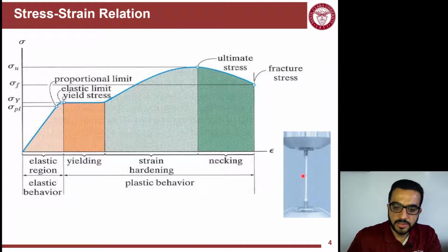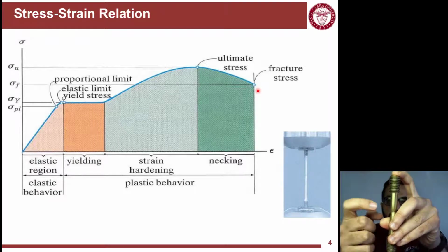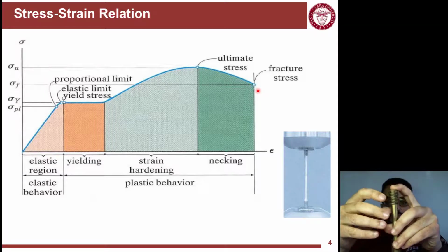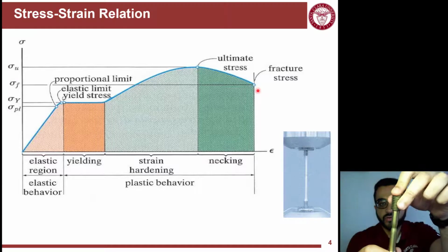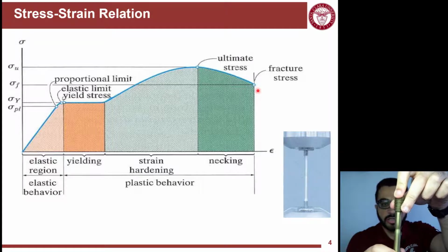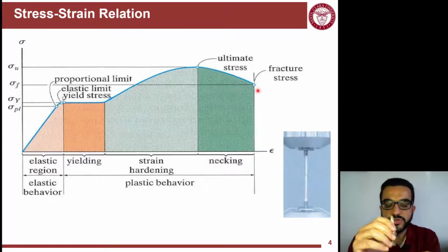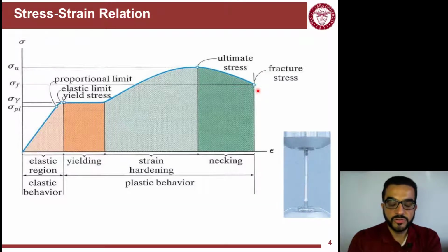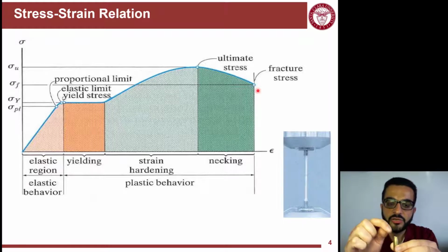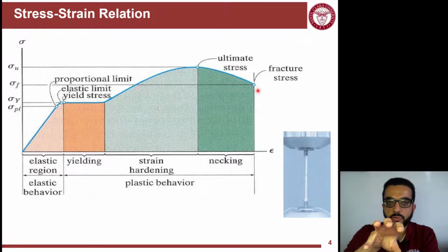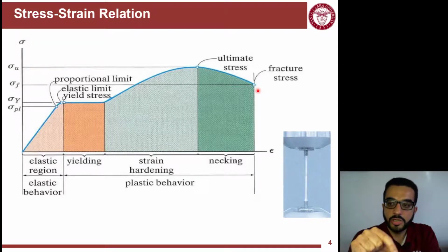So during that plastic region, what happens is this necking indicates that there is a local failure here. There's some issues with some impurity or issues with manufacturing at this specific point, and this is where the failure will start to happen. But also it's an indication that the failure will happen once you see necking, that the stresses on some angled point, so the orientation of the stresses here, shear is actually causing failure here. So we'll see when we cover transformation of stresses that while we apply here tension, so it's a tensile stress, internally the same point feels tension in this direction, but it can transform the load, and once you transform the load, there is shear stress developing at different orientation, and that shear stress is really the one causing failure here.